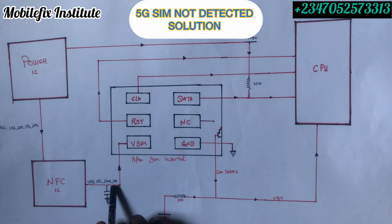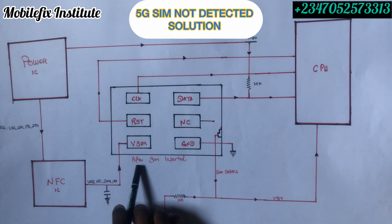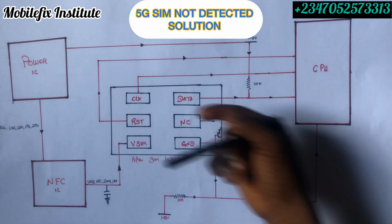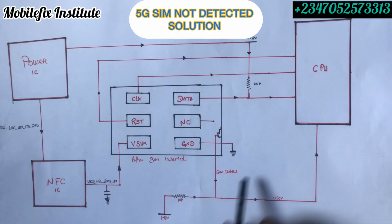And you can only get this 1.8 volts after you have switched on your phone. And not just that, you have to connect your SIM. Remember, I wrote here after SIM inserted. So before you get these voltages, you have to insert your SIM. You insert your SIM, you switch on your phone. That's when you get these voltages.